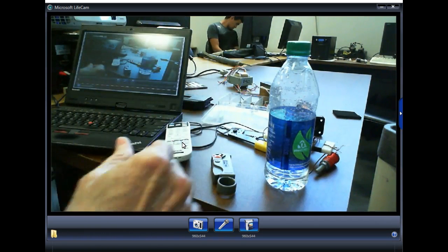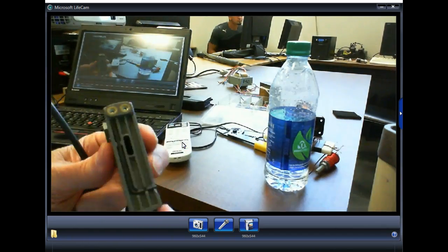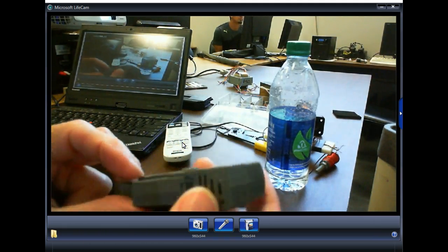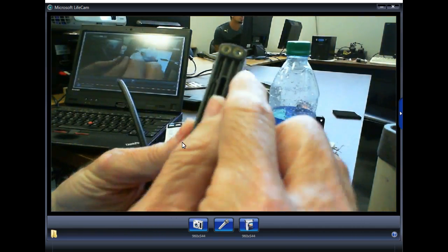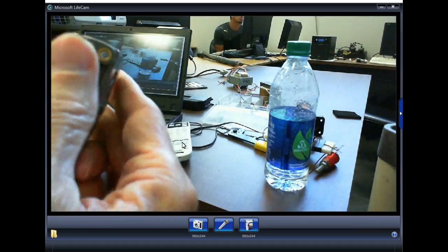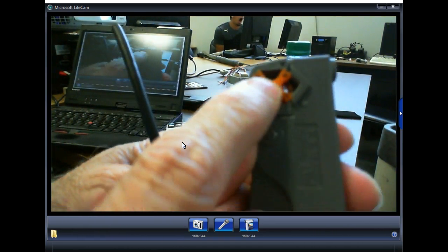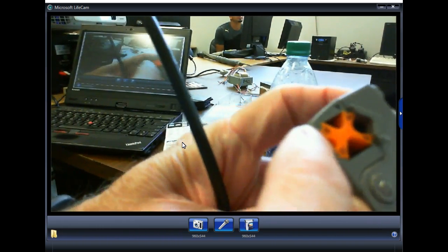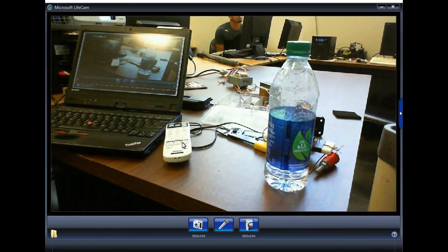So we have special strippers. This is a coax cable stripper, which is pretty neat. You literally adjust it, so it takes a little while to adjust it, but it's got two blades in it. It comes with an Allen wrench, and these are the two set screws that you use to adjust the depth of the blades that do the stripping. Once you get it set, you can just move this around for RG8 or RG59 or RG6, and it will strip all those cables at the same setting.